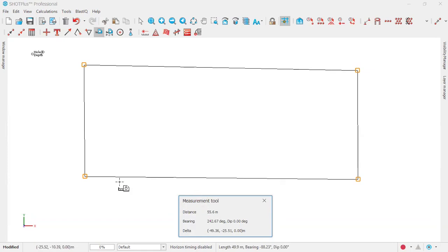So after that, you click on snap to object. This one. Okay, it's already on snap to object mode so that you can select the shape. So after that, you want to know the length. So you position it here. Okay, click on it. Then you hover it on it, up to here, then you left click again. So now you know the distance for this shape. Okay, so 66.9. Someone can write it somewhere. 66.9. You leave it.